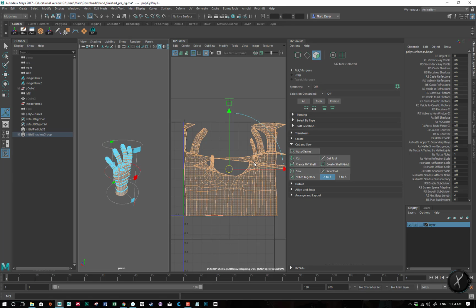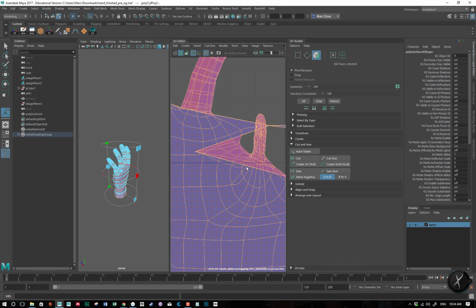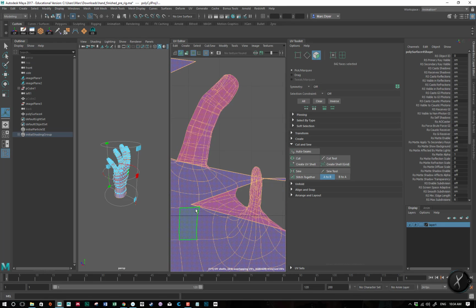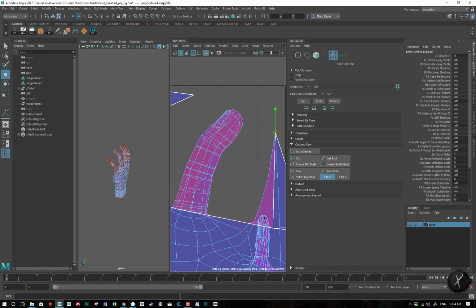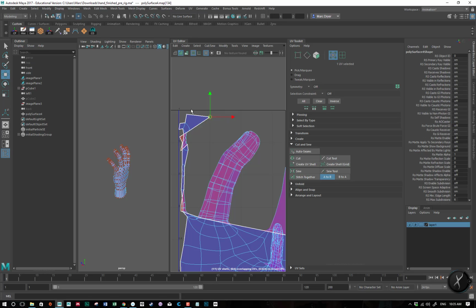And how can you see if there are overlaps? Well, one way you can do it is turn on this button here, and this shows one side is red, one side is blue. So the outside of the model will be blue, the inside will be red, and if they overlap, then you get a kind of purple. So let's see if we can get a perfectly red piece here. So if I just take one of these UVs and move it, oh, there's a little bit of red down there. Oh, probably here we can get it.